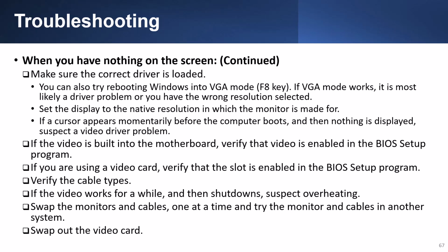You should also verify the cable types. If the video works for a while and then shuts down, suspect overheating. Try swapping the monitors and cables one at a time, and try the monitor and cables in another system. And if possible, swap out the video card.